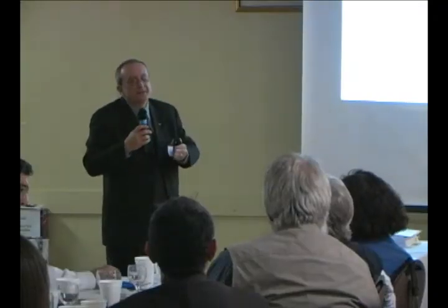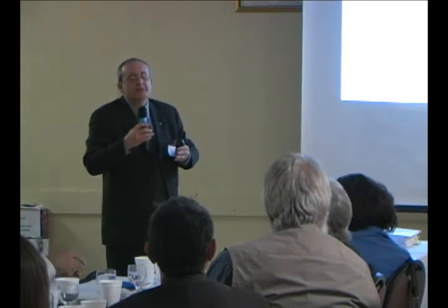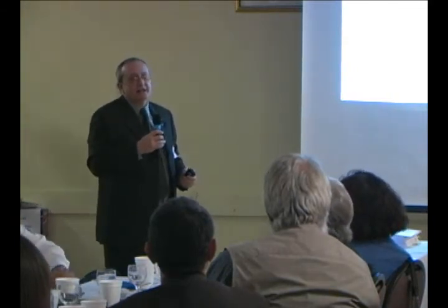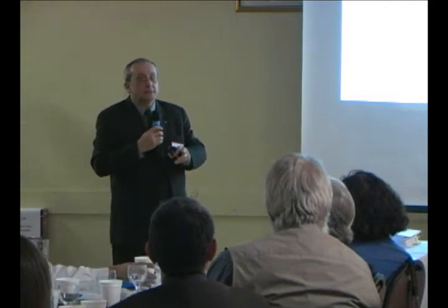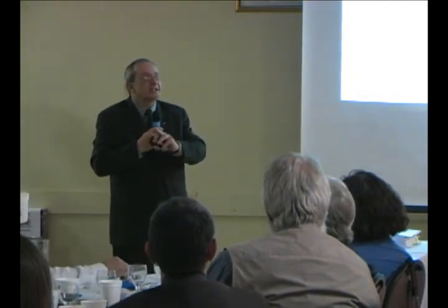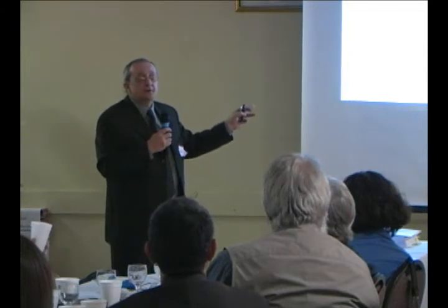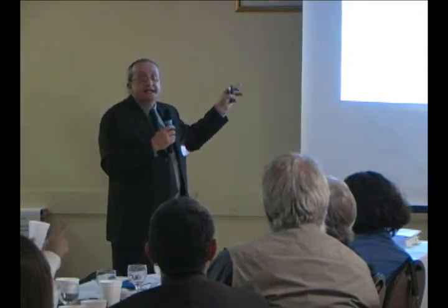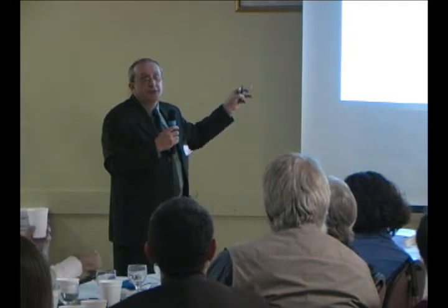Certified wood record, Craig touched on this. Again, there's a chain of custody for the wood that you have to show from the forest where it was grown and cut down all the way to when it arrived on site. If you haven't got it and they've delivered materials fabricated from plywood, you can't get it after the fact. And that's why you don't pay them. You don't pay them 90%, 50%, you don't pay them nada for that particular portion, because you may have to pull it out and you'll have to do it all over again because you're looking for this.